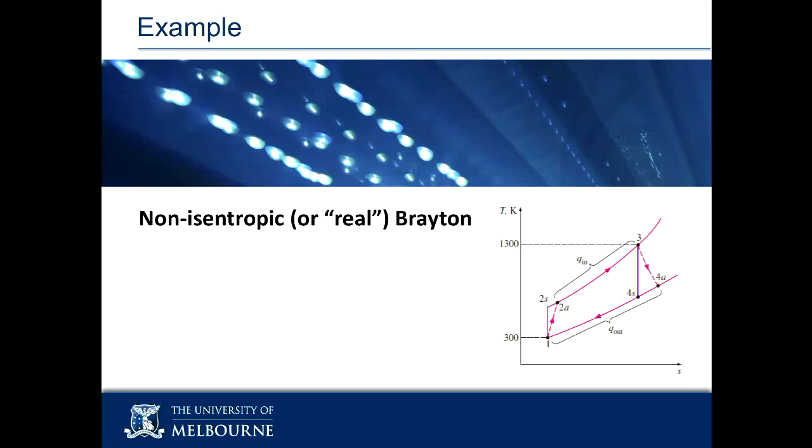If we're changing 1,000 degrees, which can happen in a compressor, or 800 degrees, you end up with some errors. And so there is a tool or a table that one can use. Yay, another table. There's a table that one can use and a trick that one can use if you can't assume that Cp is constant.